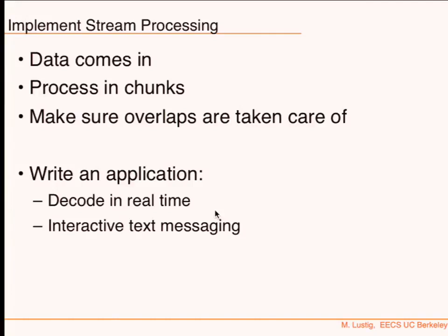There's delays there, some valid, non-valid values. Now that you have to stitch these different segments, different buffers, you have to make sure that the receiver doesn't know or doesn't care that it's broken into parts. Okay? Because we're going to do real time. So you'll have to deal with that, and that takes a little bit of thinking and some time. Okay? So you need to make sure that there's overlaps.